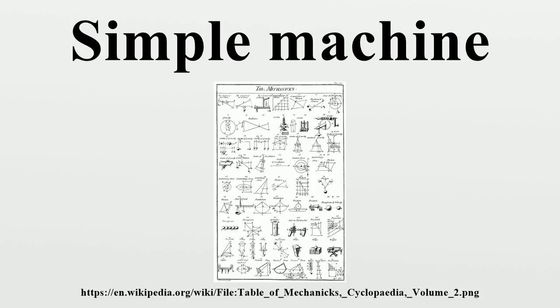A simple machine uses a single applied force to do work against a single load force. Ignoring friction losses, the work done on the load is equal to the work done by the applied force. The machine can increase the amount of the output force, at the cost of a proportional decrease in the distance moved by the load. The ratio of the output to the applied force is called the mechanical advantage.